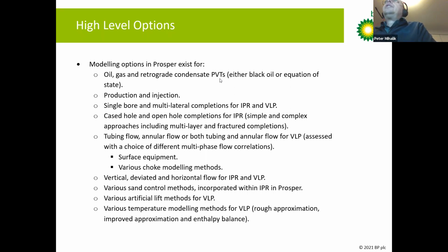We have those options available to us in Rumaila because we typically have wells without packers, although that is going to change over time. Elsewhere around the world, most wells have a packer to protect the annular space, and the production will be basically up the tubing. And you can assess vertical lift performance, of course, using various multi-phase flow correlations, and you choose the appropriate correlation for your fluid type and the kind of flow regimes you expect.